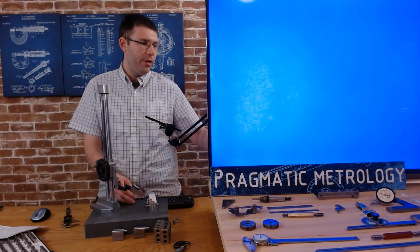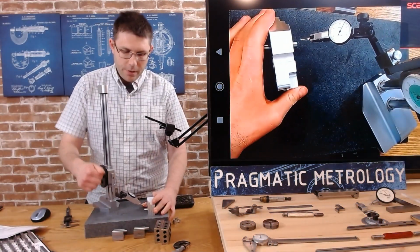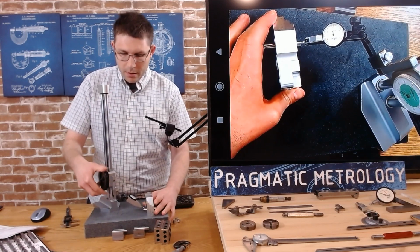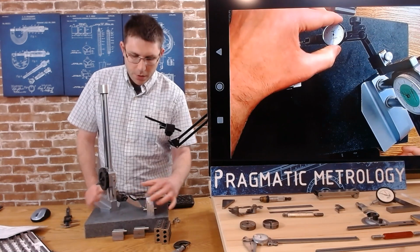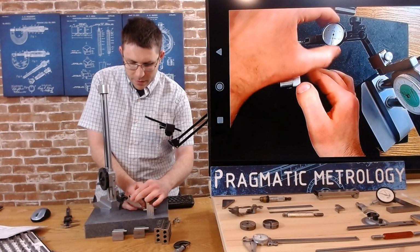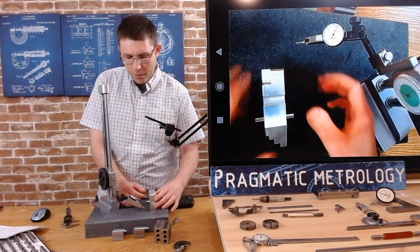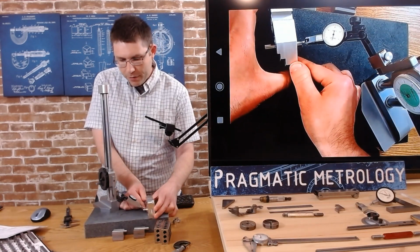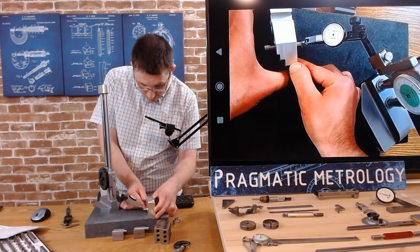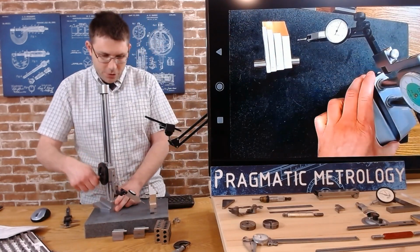Another way you could do this, I'm just thinking out loud right now, is you could zero it on one side. Actually, I haven't swept it yet, so I could zero it on this side. I have 0 on my indicator at the top of the pin, and then I flip it around. Do I still have 0? No, I do not. I have about 2 thousandths difference. And we can flip it to this side and check.